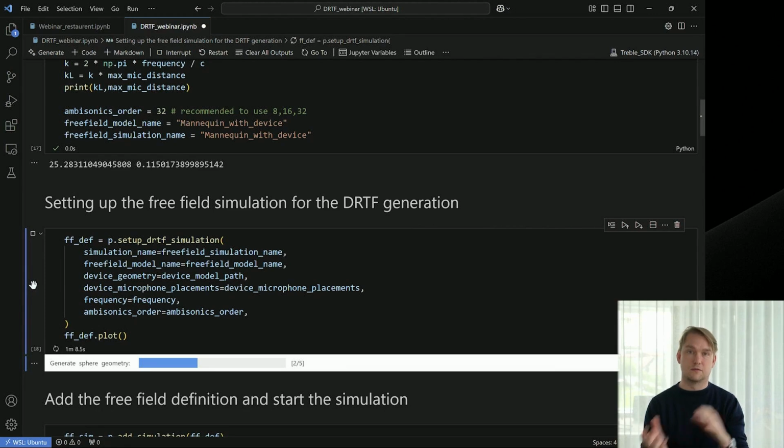And here we have some very fine details, which means that the mesh is also fine. Typically, that's a pretty big bottleneck when you're doing very large room simulations, because your computational time depends on the smallest element in your simulation, and they will be very small for these types of devices. But by pre-computing the device, we run the simulation beforehand, and then include the device in the room with a post-processing step, meaning that your small elements don't affect your runtime.